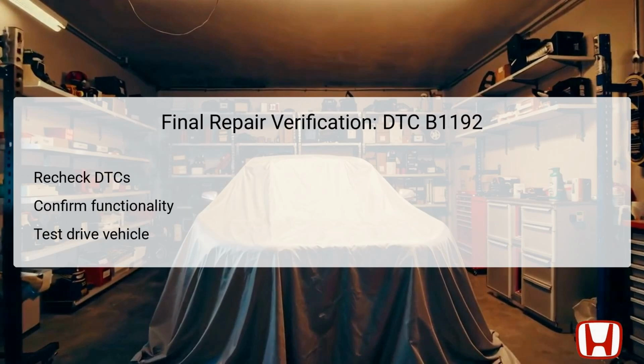Once all repairs and necessary parts replacements have been made, it is essential to verify that the issue has been resolved. Start by rechecking the DTCs using the HDS to ensure that DTC B1192 is no longer present in the system. This verification step confirms that the repaired components are functioning correctly and that communication between the gauge control module and the battery sensor is restored.